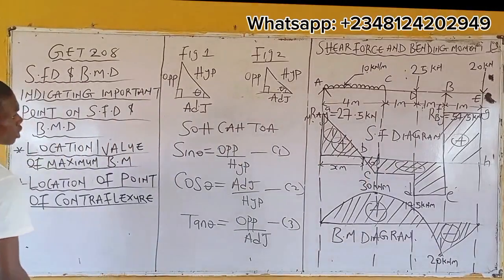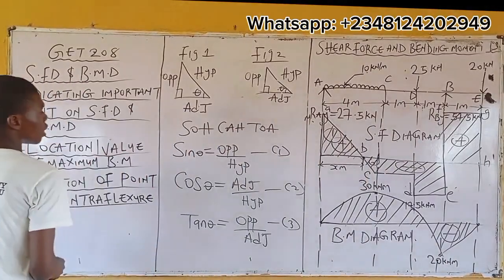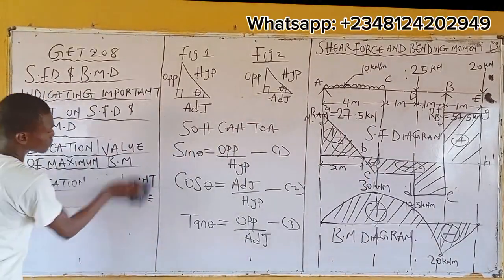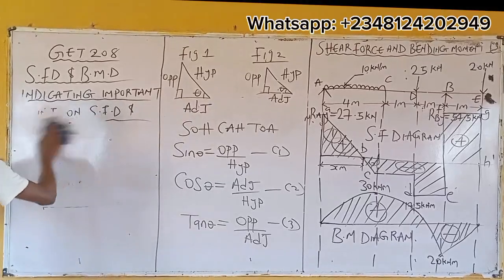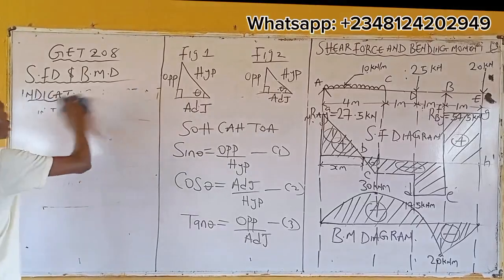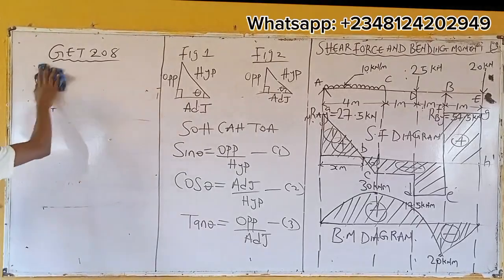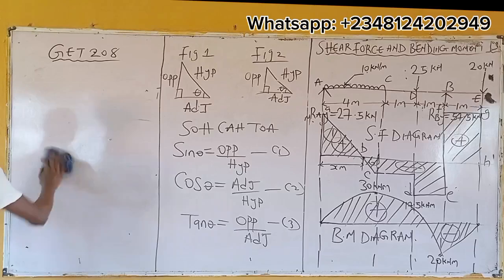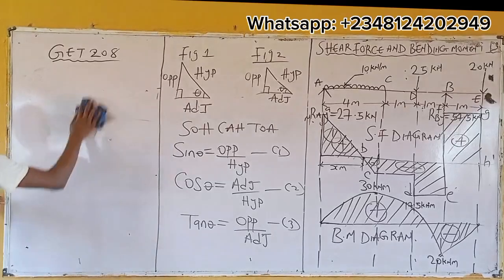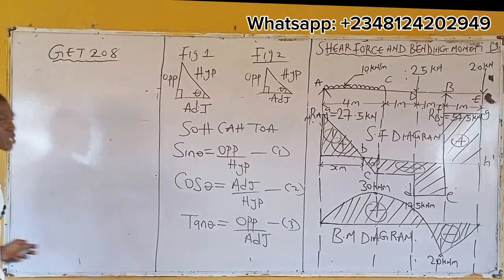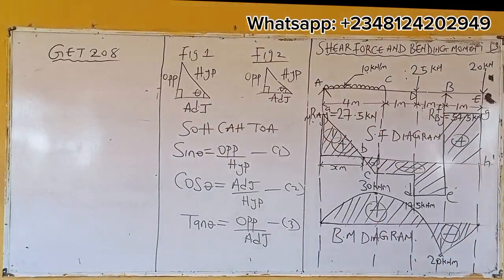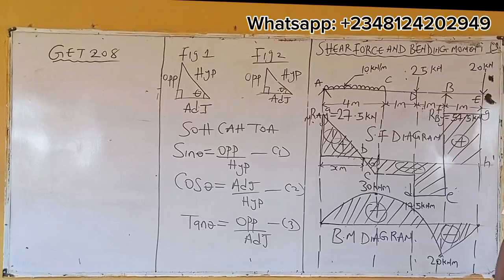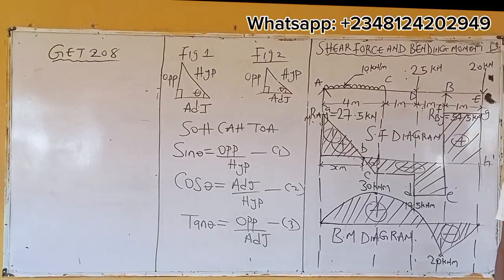Now let's bring this diagram out. From this diagram and this shape, what length are you considering in your shear force diagram? 4 meter. What type of load is it loaded with? A UDL. So that's a hint for you. Whenever you have a beam subjected to a UDL, most likely you have maximum bending moment.